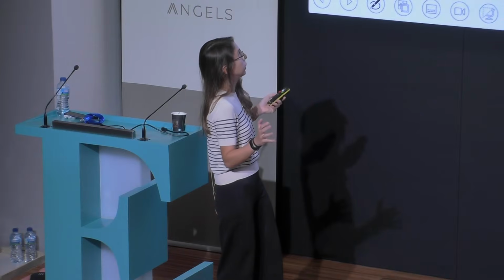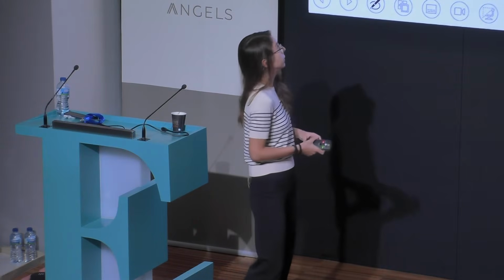This is also the frequency regime at which some other well-established technologies work already, such as radar, space technologies, and some other ones, which means that there's already plenty of connectors, room temperature electronics, generators, cables that exist and that can be leveraged to work with superconducting qubits. So even though many of these have to be adapted to work with superconducting qubits, this allows one to already start with a threshold that's much lower than if it was a completely different frequency regime.